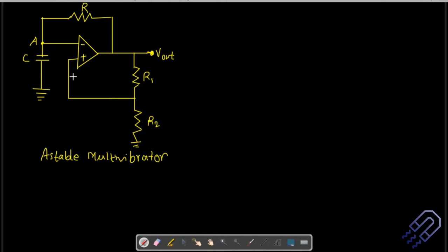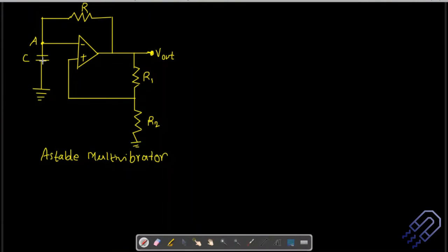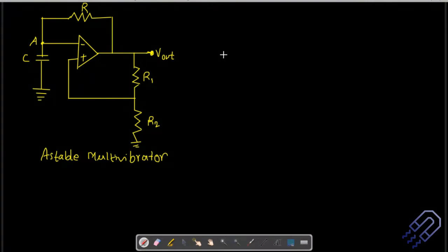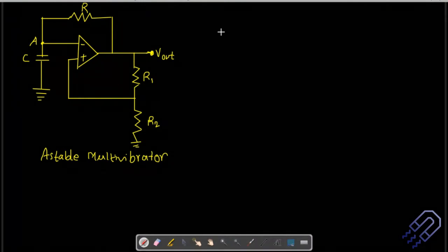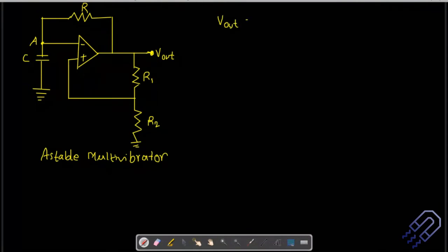So when I ask you for the circuit, you can draw this. And the Schmitt trigger, you should know, I've just drawn separately. If you don't consider this E and don't consider this R, it is nothing but a Schmitt trigger. This is based on how triggering happens, and that's why we are going to use a trigger. In general, this V out, if we are not considering any kind of input in the initial stages, is equal to V saturation. This is the initial condition.